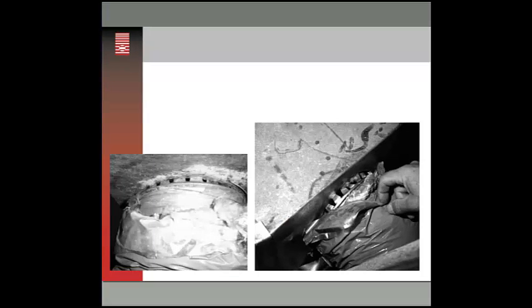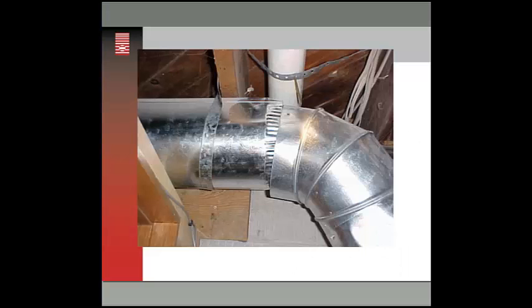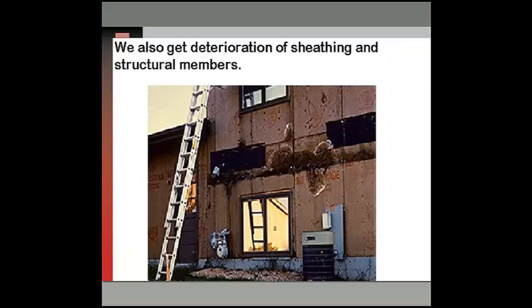And there are lots of penetrations. You can go through buildings and find these little air leaks that will add up all through the building, full-blown disconnects, no attempt at sealing at all, and it can cause durability issues. This is a shot from a house in Minnesota that had ductwork running through the ceiling of the first floor, and they had a full-blown disconnect.